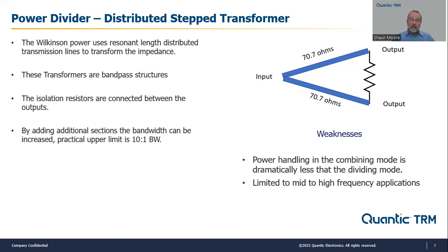This really does a very good job as a power divider, driving higher power levels, because really the only loss that you have in this circuit is the ohmic loss of the copper, as well as the losses in the dielectric itself. So therefore, it can be quite efficient as a power divider for fairly high frequency components. This can be built in either microstrip or strip line.